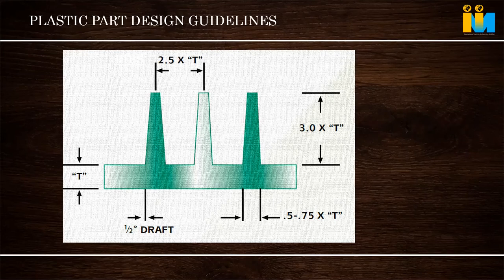If you make a part without a radius, it may take a load of 10 kg, but with the radius it can take 100 kg, not even 20 or 30 kg. That much drastic difference. Yesterday we saw the loading capacity of a stressed part and a non-stressed part. So radius is one of the important contributors, for flow and for loading, and to avoid cracks. And in this area, we were talking about notch sensitivity.